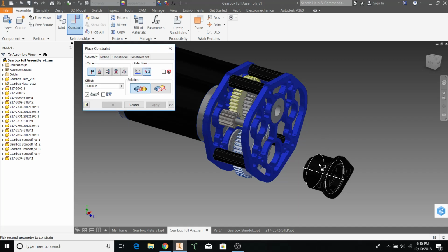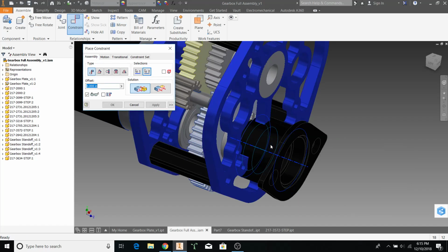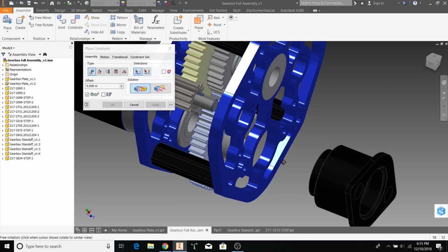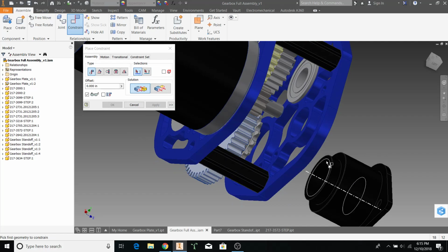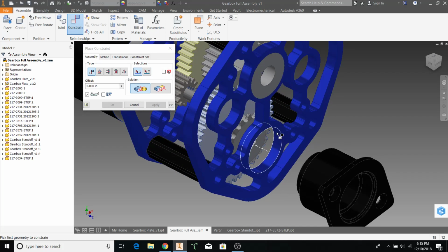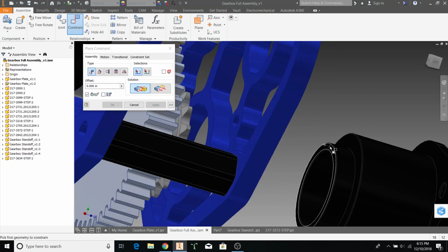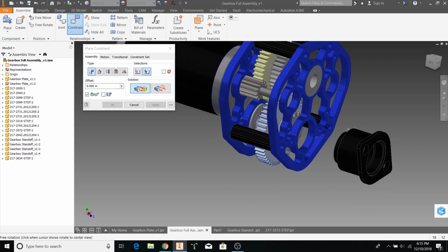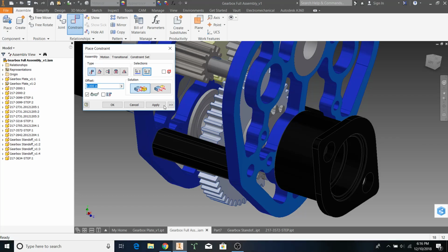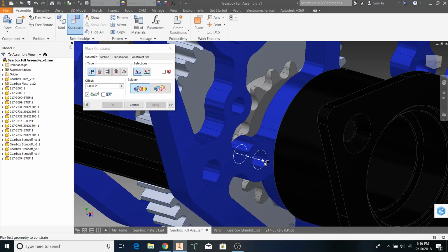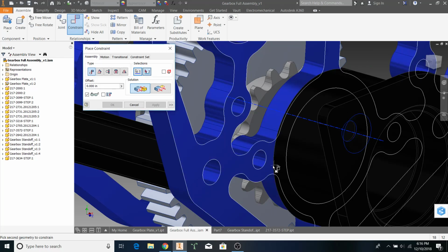We're going to constrain it concentrically here and here. Drag it out a bit. This little nub right here is the same outer diameter as a bearing, which would fit in right here, 1.125. So what we can do is do it in two ways. This will be my preferred method, is connecting this outer face to this face right here. And now, finally, this bolt hole that we made here aligns perfectly with the bolt hole here.